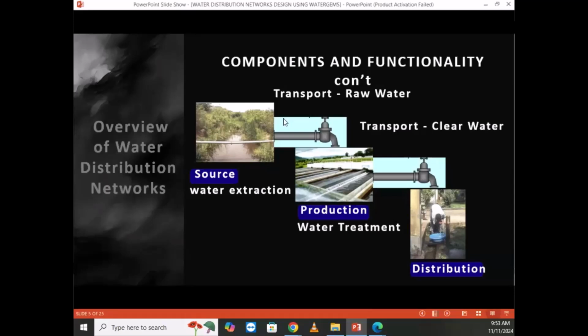Yeah, adding on your explanation, as you have said, we are doing it the other way too. When we are doing the population projection and the water demand assessment, we refer to the domestic water demand, which is the base. Then, according to the design manual of the Ministry of Water in Tanzania, there is a guide with some criteria.